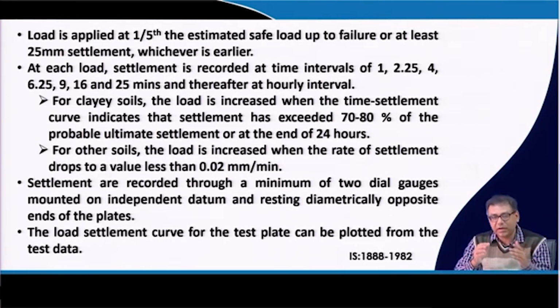That means, for clay soil, the next increment can be applied after the loading has been held for up to 24 hours. So, maximum we can go for 24 hours, or if we see that the settlement exceeds 70 to 80% of the probable ultimate settlement. Again, as I mentioned, we have to get an idea of what the probable ultimate settlement would be. Then if it reaches 70 to 80% for that particular load, you stop there, or else you have to keep it for 24 hours. As we know, for clay soil, it is a long term settlement.